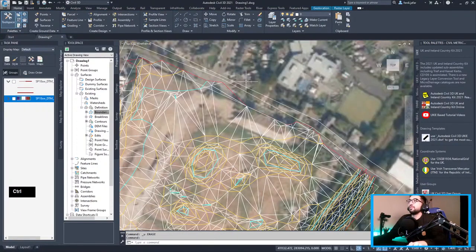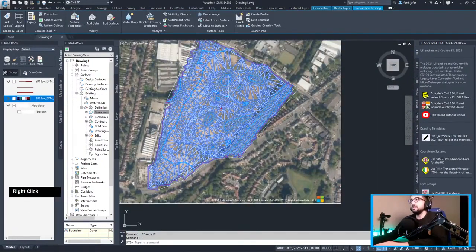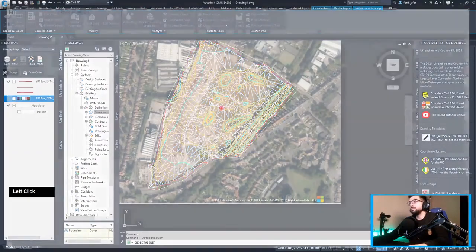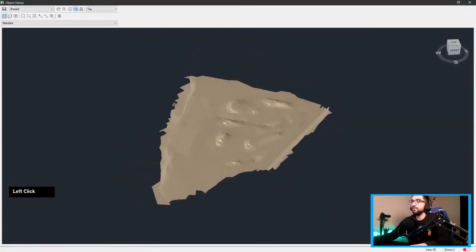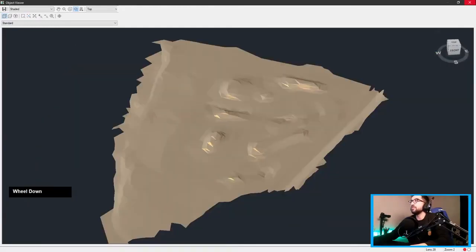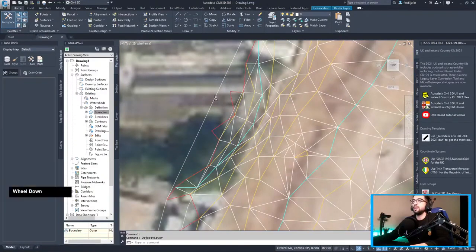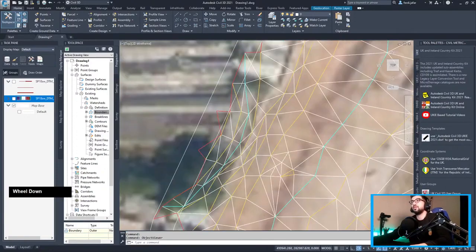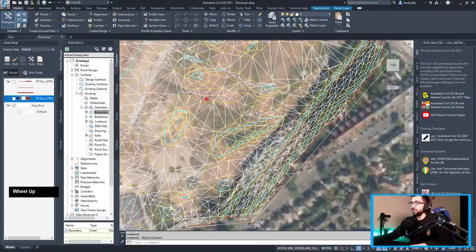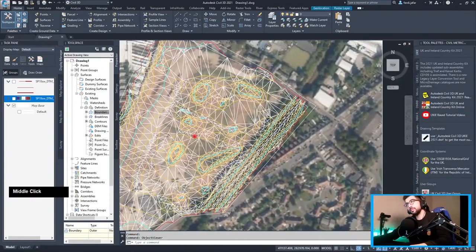I deleted my boundary by accident. Is this my boundary line? No, this is my boundary line. Okay. So it has been fixed, and if we go to object viewer, you can see that we have our ground model. Now, if you want to fix these triangles, then what I would suggest is just make sure that you create new points on the existing surface, like where your line is, just so you can fix those triangles. And sorry about that.